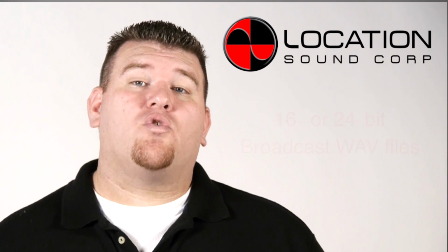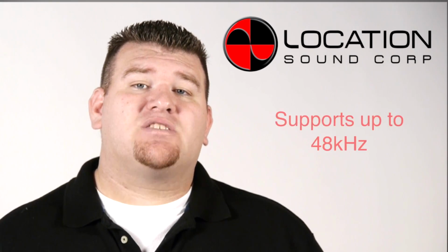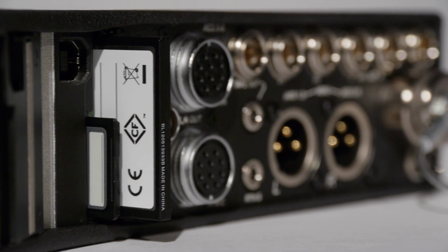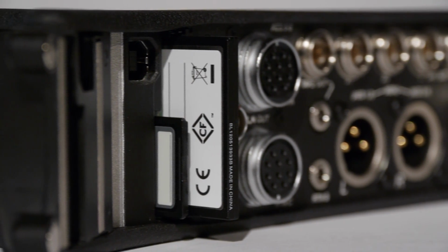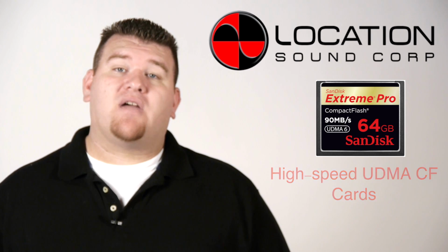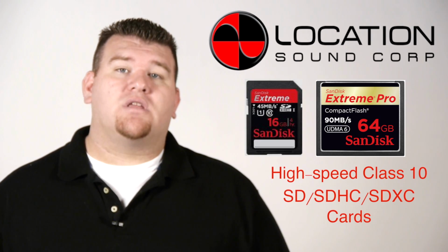The 664 records 16 or 24-bit broadcast WAV files with extensive metadata and supports all production sampling rates. It records simultaneously to both compact flash and SD media cards and has the option for different track combinations to each card type. Sound Devices recommends high-speed UDMA compact flash cards and high-speed Class 10 SD cards for higher track count recording.